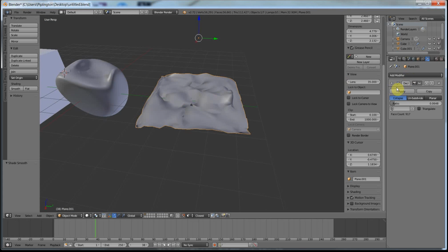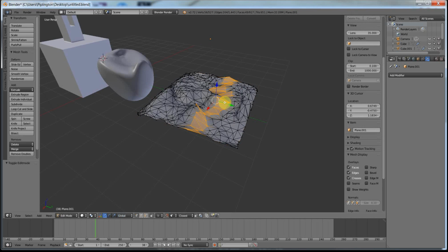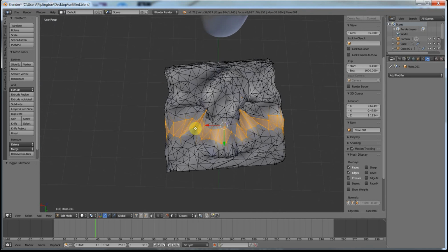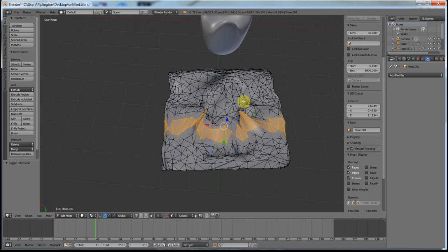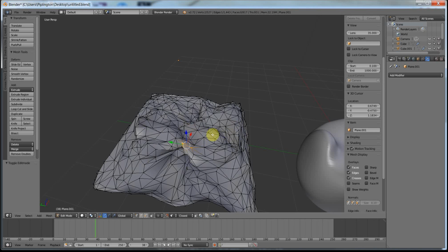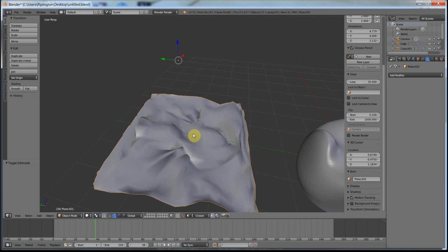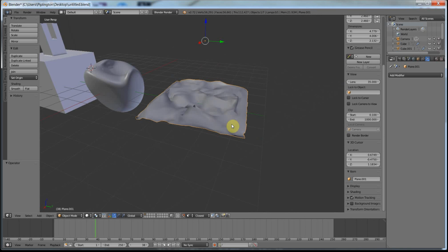It might seem like a good idea to use that on maybe this, but really it messes up the object shape. If I apply it and look at it, it makes loads of triangles, it merges vertexes randomly, and it's really hard to then fix from here. But we can bring it down to a fairly low poly if it's a really complicated object. So I'm just going to do that, and we can look at the different types.